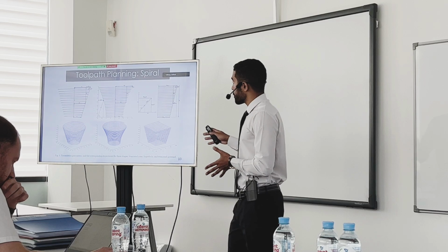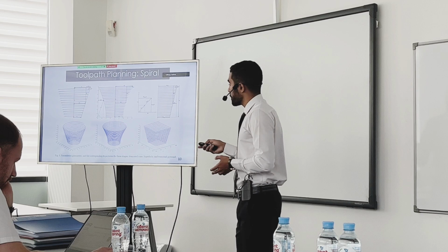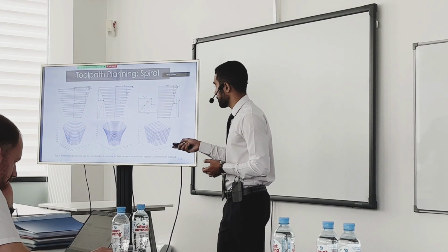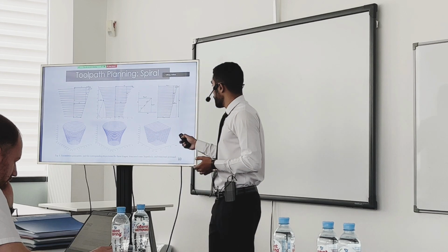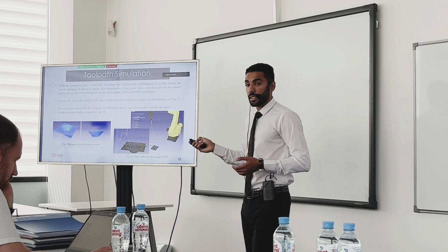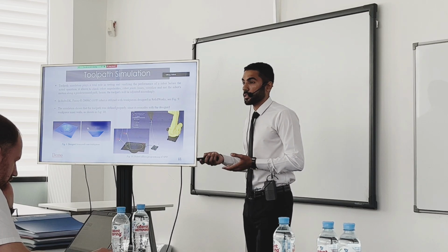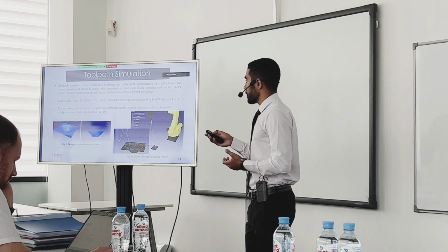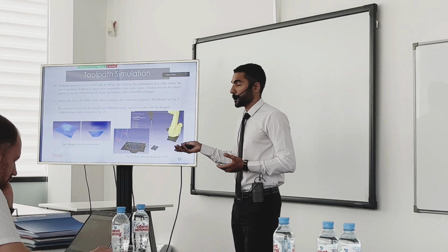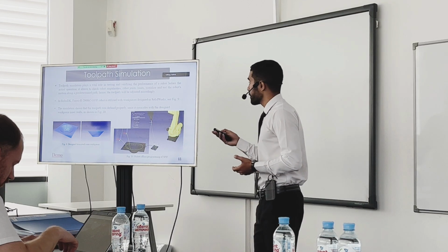So in this research, I'm using the spiral layout, and I considered 3 different profiles as test cases, which are the truncated cone, the hyperbola, and the truncated pyramid. After generating the tool path, it was very important to check the feasibility of the generated trajectory, because later this will be applied to an actual robot operation. So to check, for example, the robot singularities and the robot joint limits.